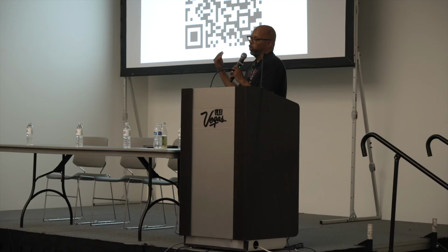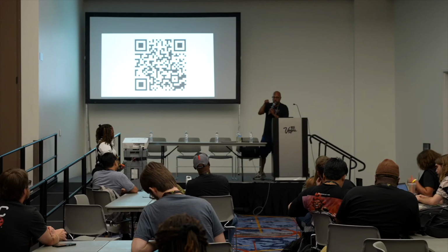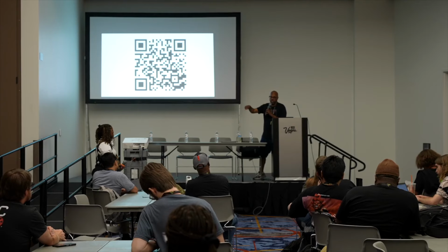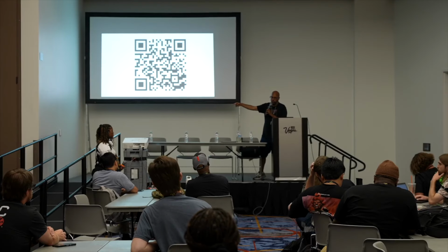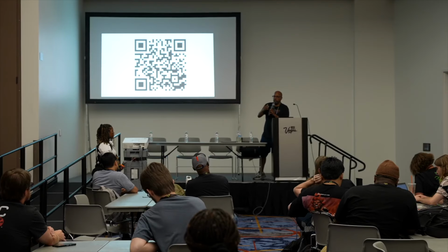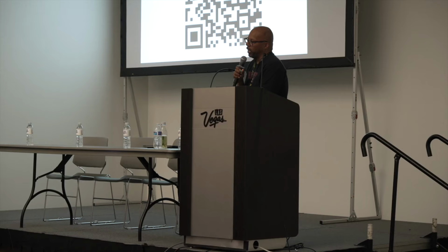You can get runtime information, like we use Embedded Trace Macrocell, where you can follow all the branches. I have a paper where we follow the branches to see if malware is running, because if malware is running, it will branch to the wrong location. If somebody did a buffer overflow and changed a return address pointer, it will jump somewhere weird. So with one of these debuggers in real time, you can have another processor reading the branch addresses through JTAG or SWD. Those exist. I just didn't talk about it.